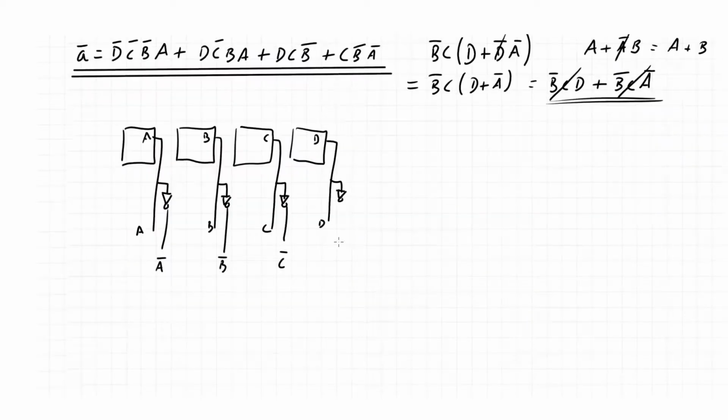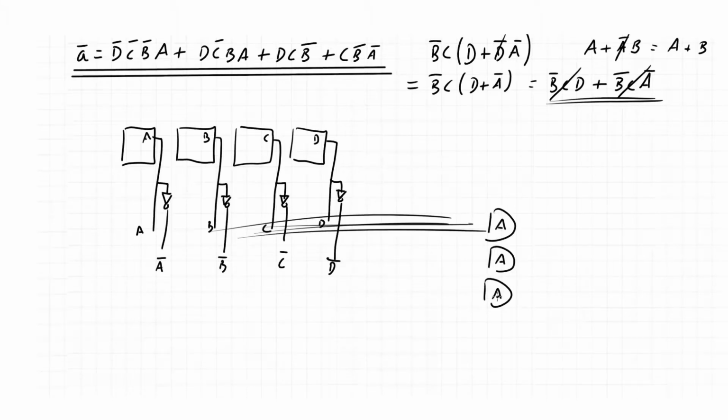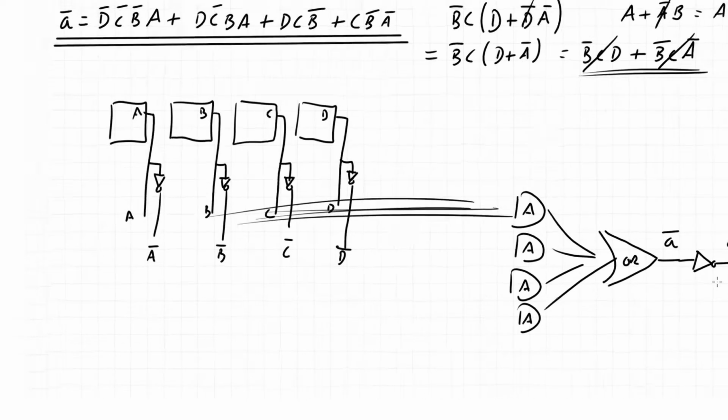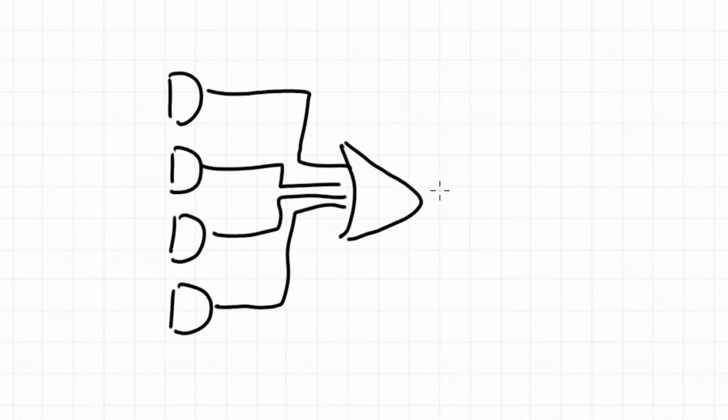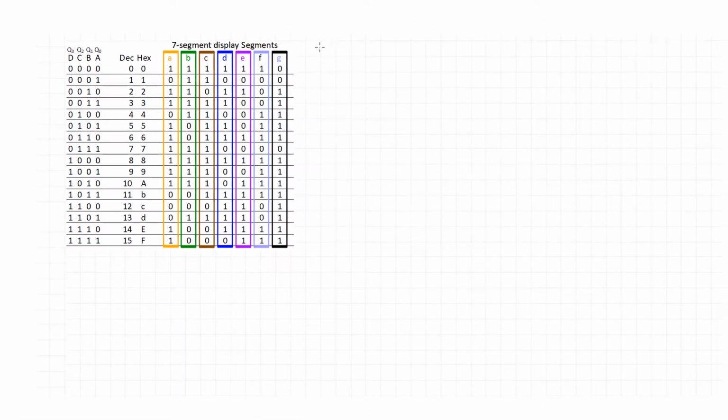So there's the expression for not A, and we're going to tap off from the counter logic like before. And instead of using an OR gate, which gives us not A, we could use a NOT gate after to give us segment A. But an OR gate followed by a NOT gate is a NOR gate. So we can use negative logic with a NOR gate to get the correct output.